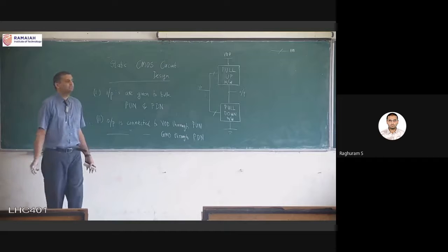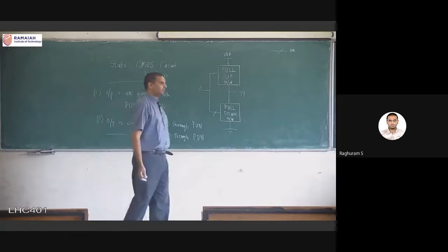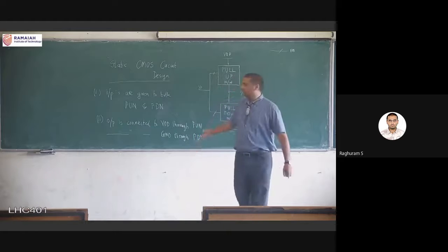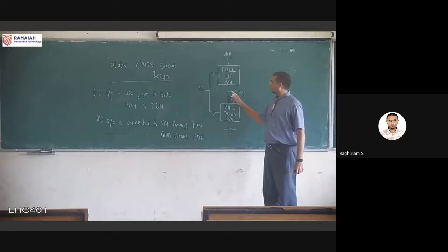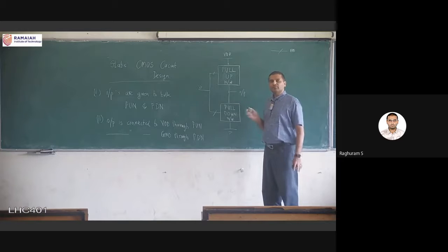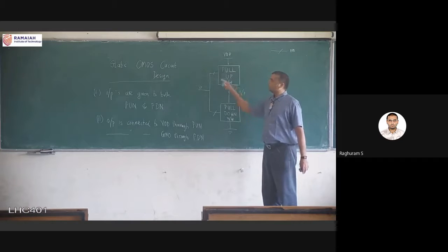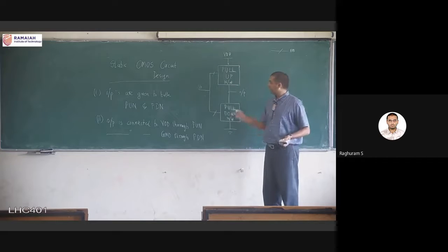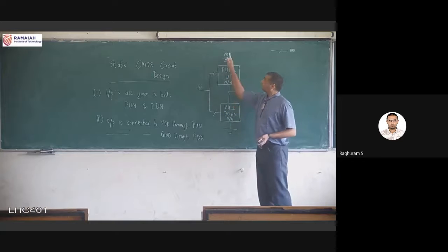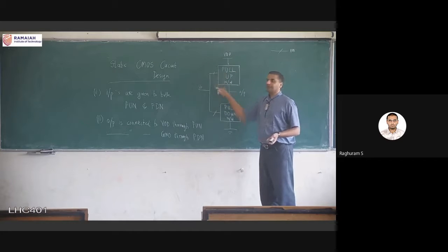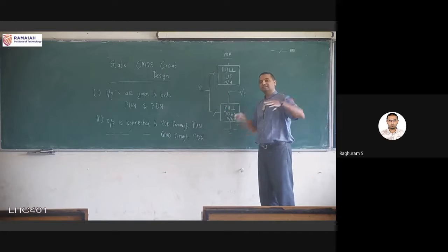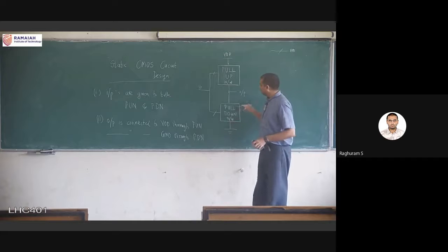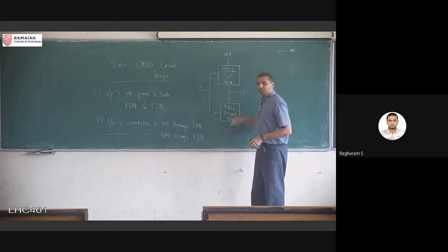This is almost a guarantee based on the configuration. If the output has to go from 0 to 1, it can only go through this network. There's no other connection, right? Output, if it goes in this direction, cannot go up to VDD. These are inputs. This is not an electrical connection. We are not allowed to drive these wires. Somebody else is supplying those signals. So through this side, it can go only to ground.